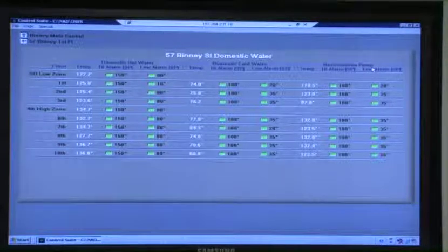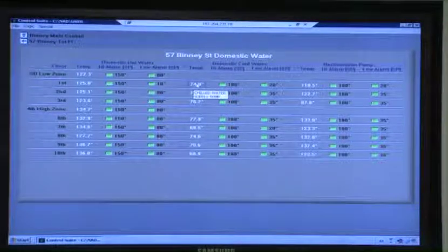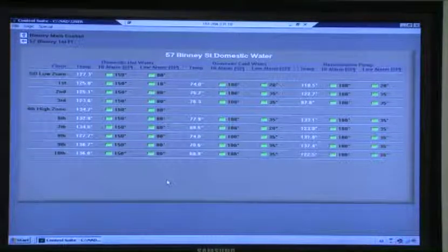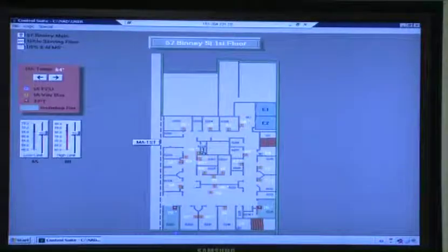Okay? You guys know how that works, right? We feed the hot water up the building, it returns back down to the heater, and we keep the loop hot. He wants to know about that. If that recirc water gets cross-fed and it's coming back way low, and this gets warmer, we know there's a potential cross-feed somewhere. Troubleshooting tool for him, okay? That's a screen that's going to be very useful for the plumbing shop to diagnose any of the recirc water issues. We're also going to be including a riser diagram. So you'll see this in a riser format, not just a blank screen. So you can look at the building and see the runoff takes on each one. Okay? That's what that's all about.